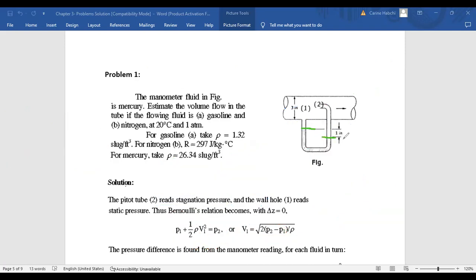For the device, you just have to read this. Once you read this, you can calculate delta P. And once you calculate delta P, from Bernoulli, you calculate V. So all of this, if you want, you can write a small program in the equipment, surely there is a small program that directly does the equation and gives you the value of the velocity of the flow. So this is the application of this device. It's used for measuring the velocities of flows.